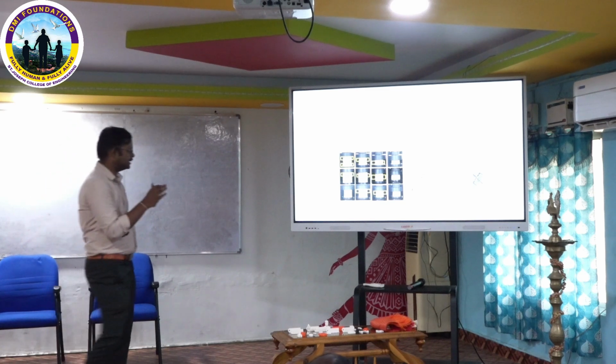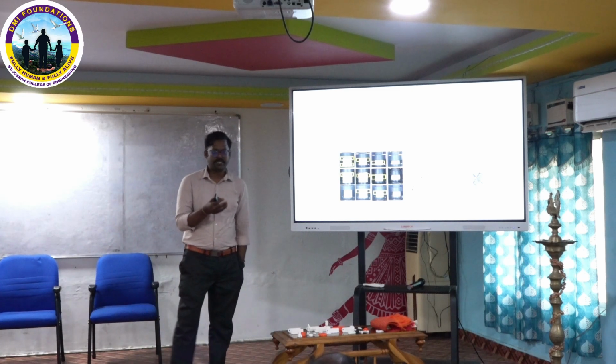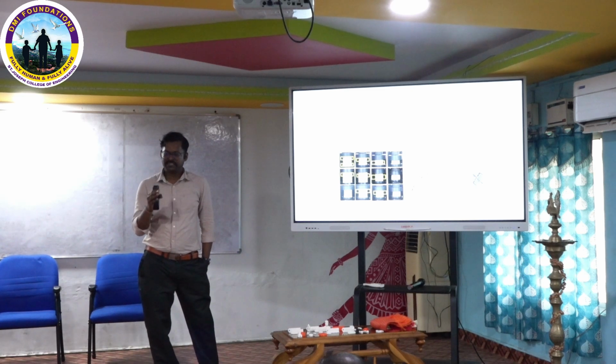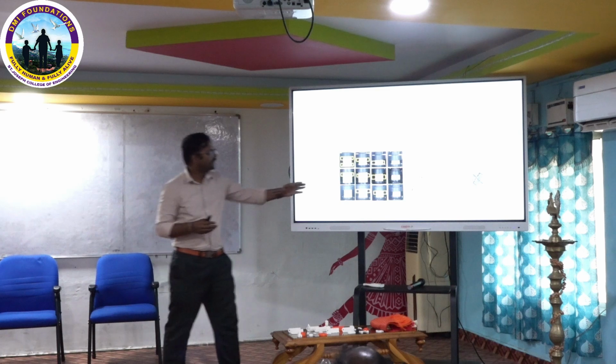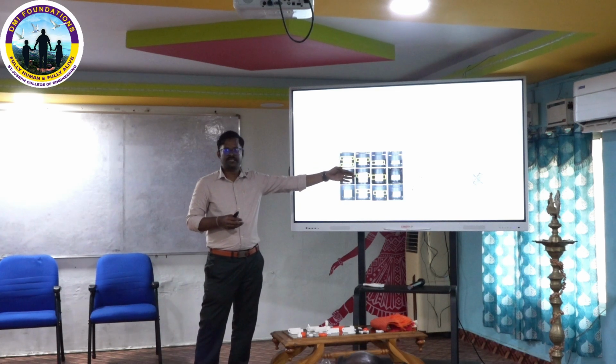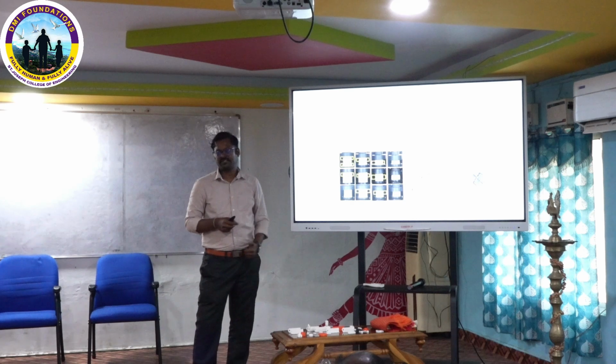Why? Because the structure has a number of struts in its topology, vertical struts and inclined struts. While compressing, the inclined struts compress in a pre-deformation manner. When it absorbs the energy, it does not let the vertical struts absorb more energy. It drags the vertical struts to buckle easier with minimum load. So we get minimum compression strength and energy absorption compared to other structures.